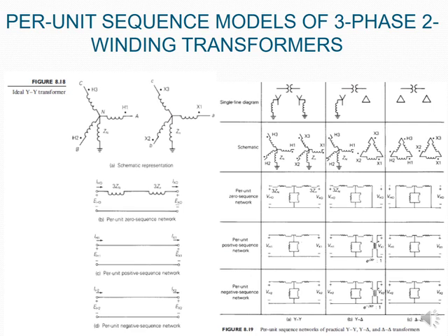So I want you to again note that on the zero phase sequence you would have those 3 multiplied by the Zn of your ground impedance, and then on the other side is the 3 phases of your impedances. Then if you go down to your positive phase sequences, there you just have one of your normal impedance, and then one would be your ground impedance. It's 1 plus 1 that you would add in there, as well as your negative phase sequence.